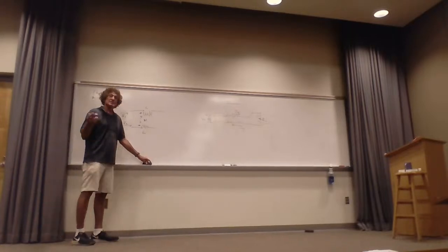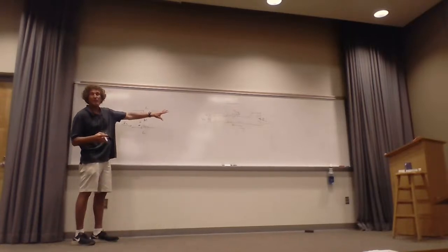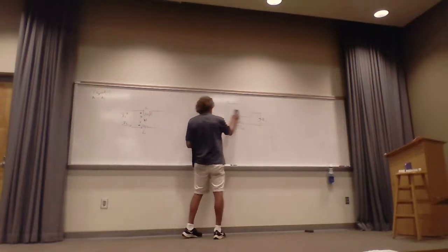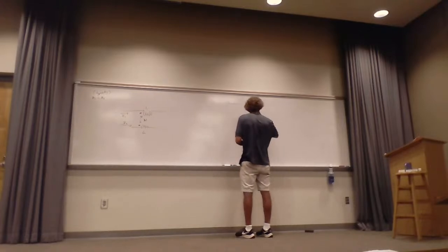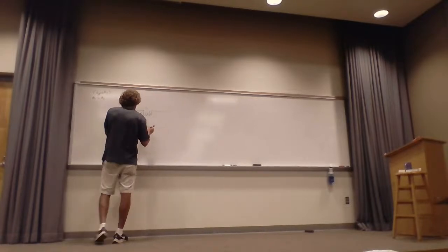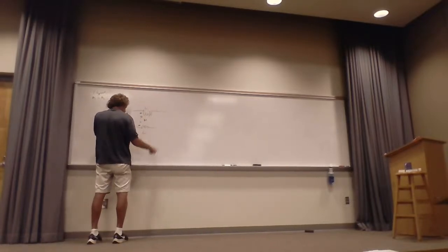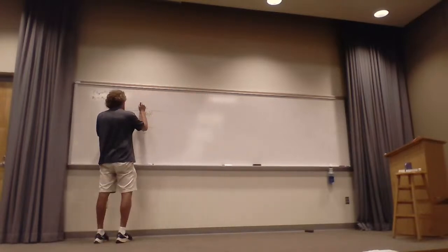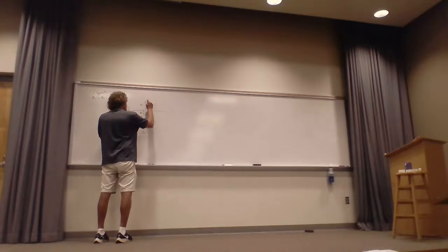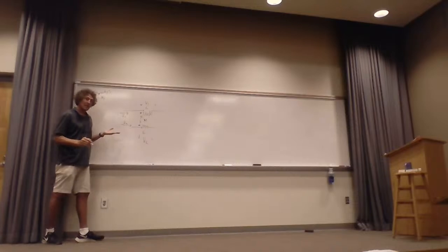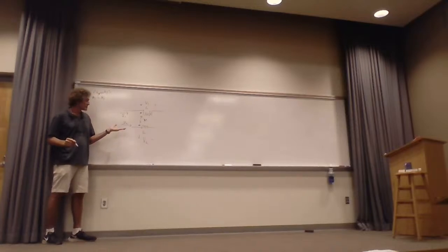So, just trying to tell you, common mode currents are bad. The way we actually deal with this, we say that we're going to have a voltage, and we'll call this plus or minus V1 here. I know I'm spending a lot of time on this. And we're going to have plus or minus V2 here. Now, remember, this is a transformer. It's got a mutual inductance and a self-inductance, right?